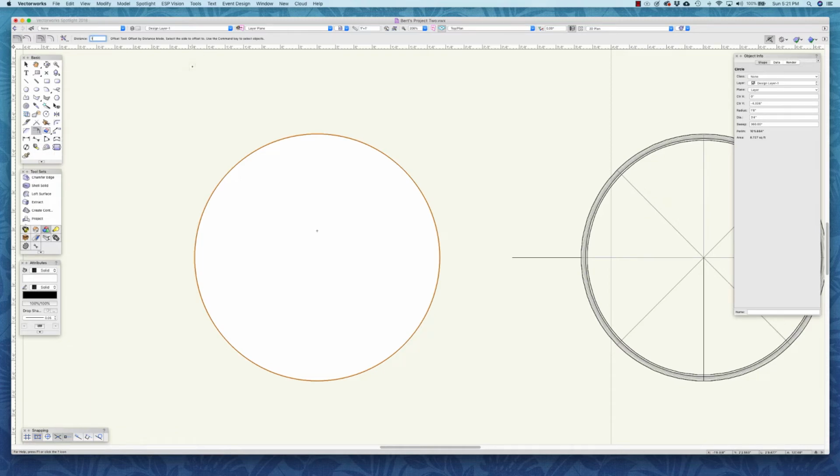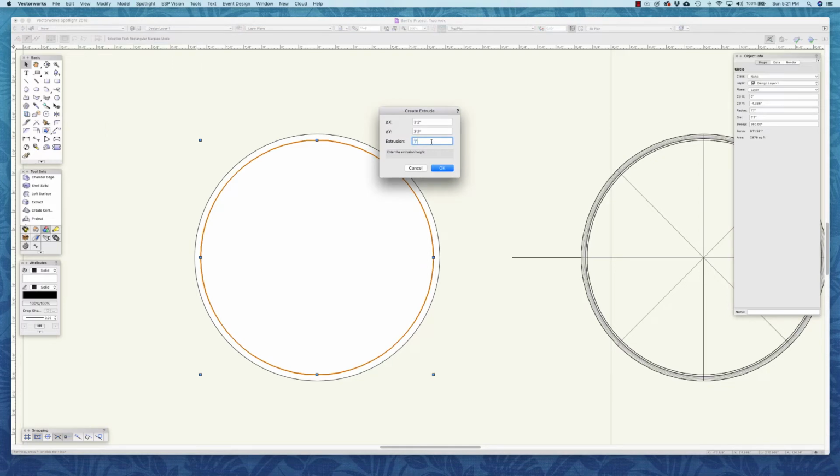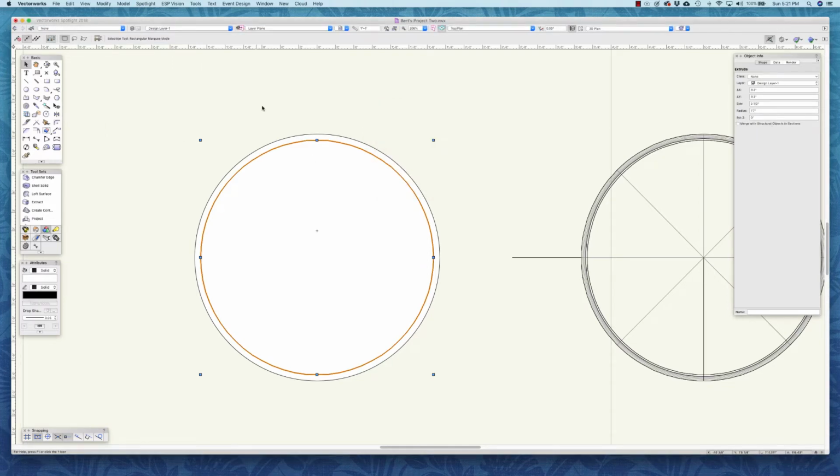And the way the offset tool works is, if I click inside the circle, it will draw a circle that's 1 inch, or whatever the shape is, that's 1 inch smaller. Or if I click outside the shape, it'll draw a duplicate shape that's 1 inch bigger. So I'm going to click inside, and it draws the circle that's 1 inch smaller. Then I can extrude that 2.5 inches to be the apron, and I can extrude the tabletop itself 1 inch.